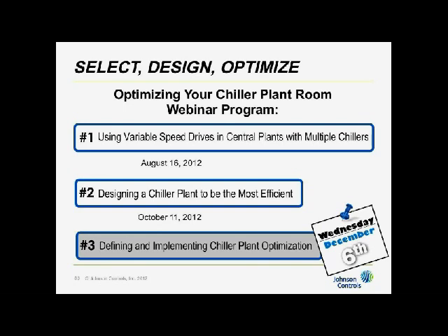Is it perfect? No. What's more perfect is each chiller, but you can't always do it. But the pressure differential one, if you're going to use that technique, I would probably recommend putting it on each chiller. Next question, VPF makes sense for only 2-way valve loads. Correct, that's correct. You don't want to use any mixing of 2- and 3-way valves because you're guaranteeing yourself low delta T, which includes not putting 3-way valves at the end for overpressurization. Add a 2-way valve for that.